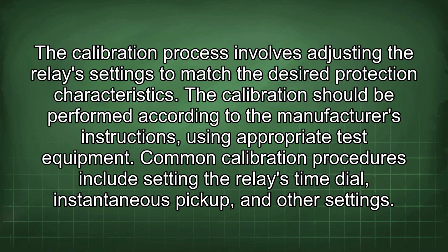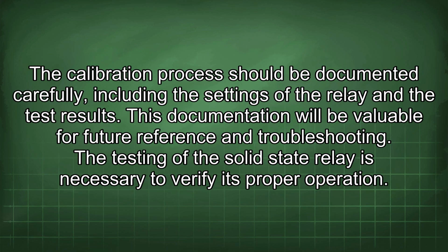Common calibration procedures include setting the relay's time dial, instantaneous pickup, and other settings. The calibration process should be documented carefully, including the settings of the relay and the test results. This documentation will be valuable for future reference and troubleshooting.